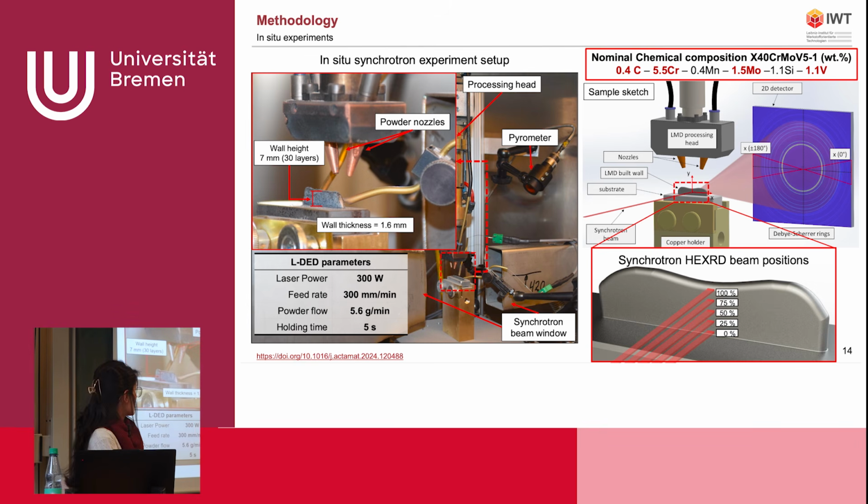So yeah, we have this node, but what was important here is that in the sample we had 5 different positions of the synchrotron beam so that we could track in situ the formation of the phases. In this case, we were interested in the carbides. We also did TEM analysis, normal SEM analysis, and so on. We know how the microstructure is different, but we don't know ex situ what the composition of the carbides is.